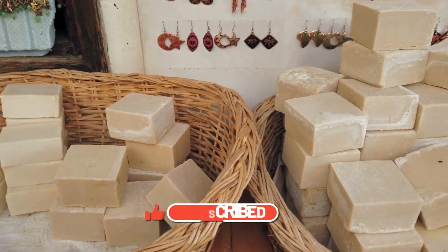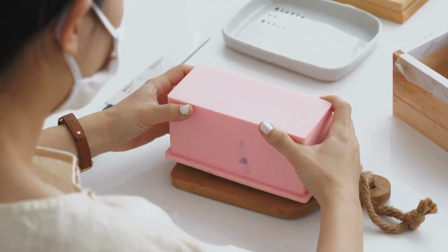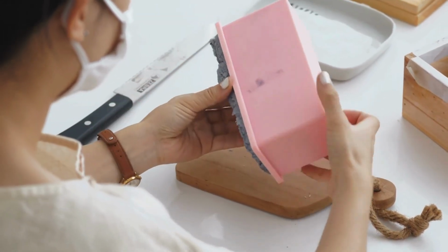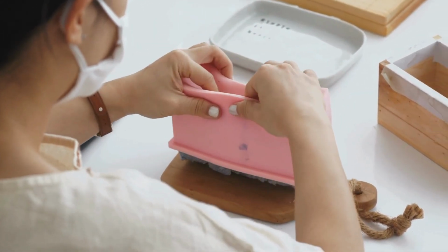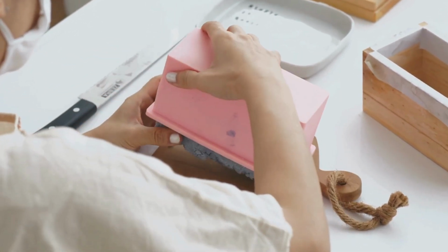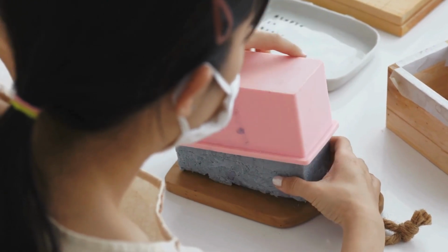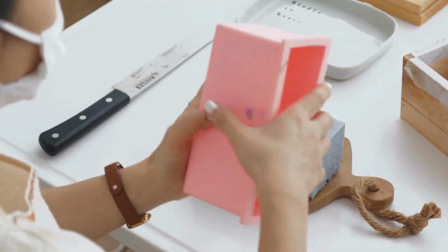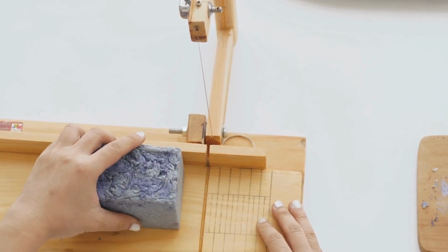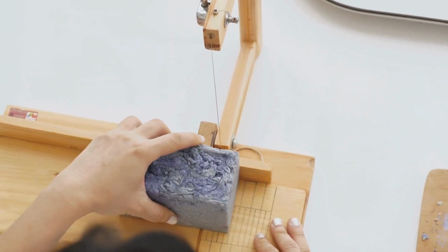After saponification, the crude soap is dried into solid soap noodles or flakes. It's mixed with additives, fragrance, color, moisturizers, abrasives, etc. The mixture is milled, refined, and blended for uniform texture. The last step is forming and packaging. In this step, the soap mixture is extruded through a nozzle. It's cut into bars, stamped with logos, and wrapped. Liquid soaps are bottled and capped.